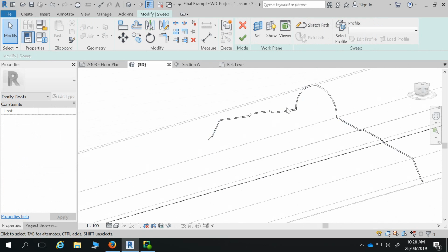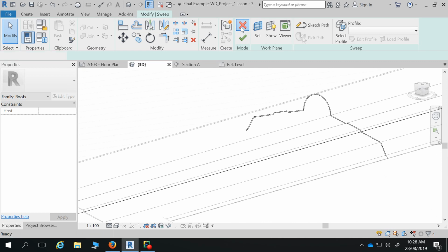So that's Russell's profile for his ridge capping. You can see it's the same sort of thing, but he's followed exactly. So how Russell made his was he snipped a picture from the Fielder's catalogue, one of the diagrams, and he imported that JPEG into his Revit, and then he actually could trace over and get those angles and divots, etc. completely right.